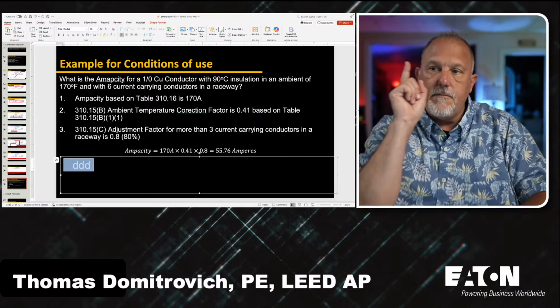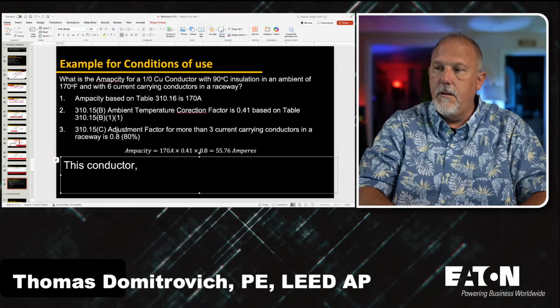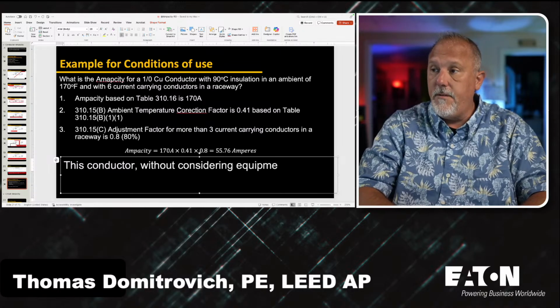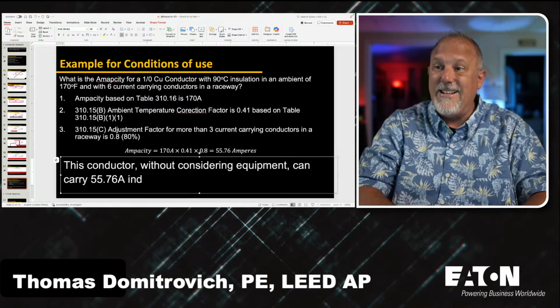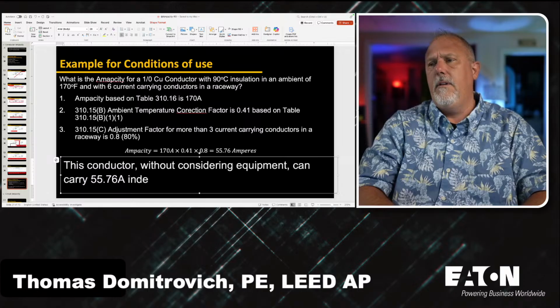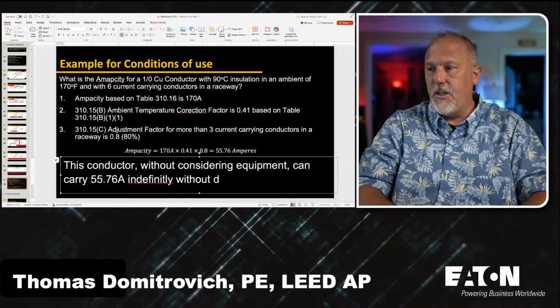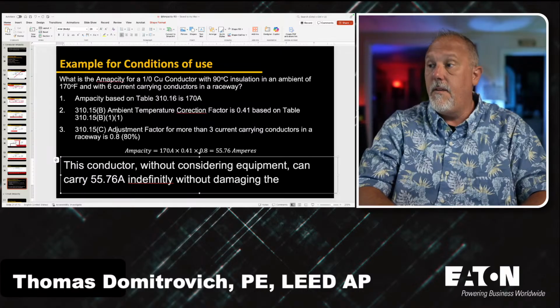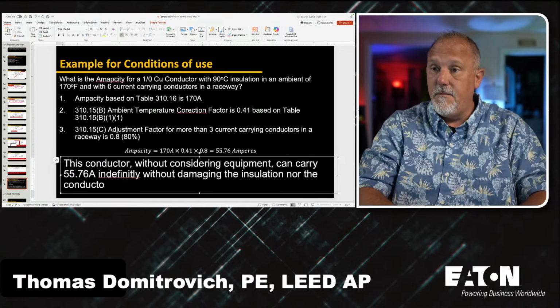And I'm going to say that this conductor, without considering equipment, can carry 55.76 amps indefinitely without damaging the insulation, nor the conductor itself.